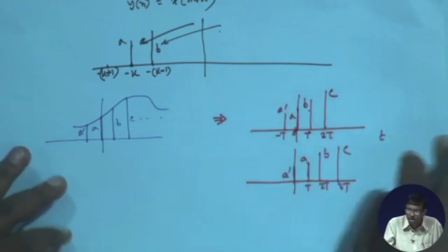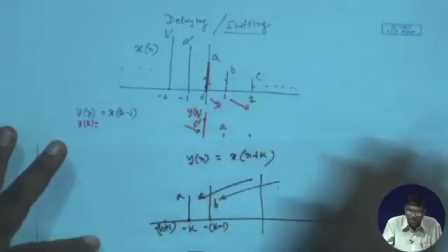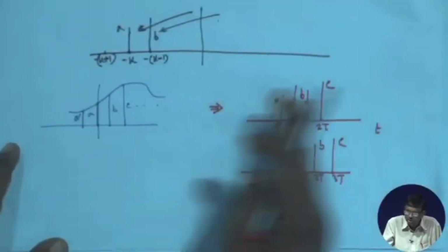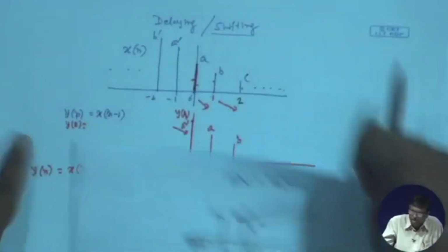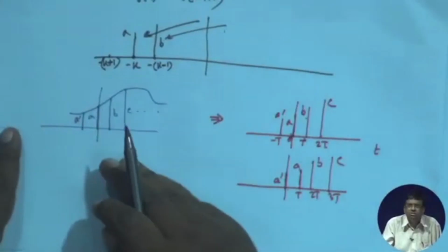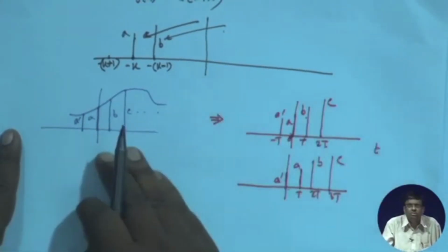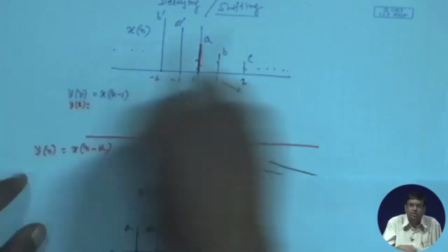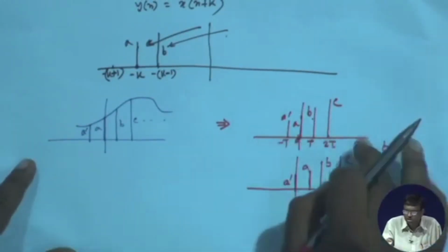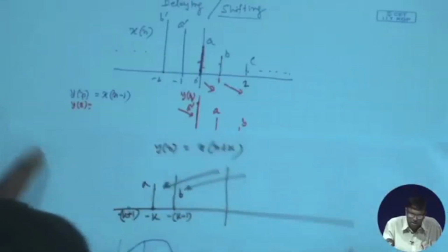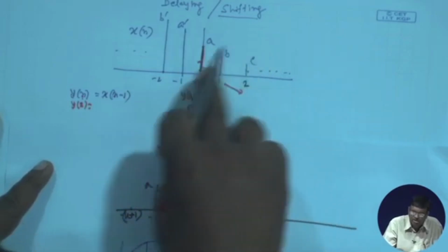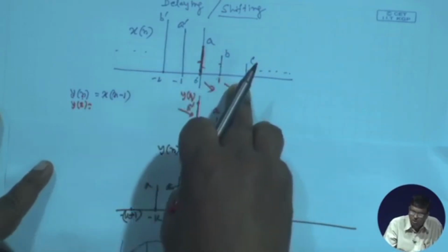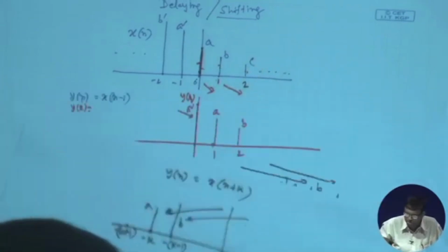Okay. So, if it is a pure time signal, shifting the sequence actually means that in the time domain the signal is delayed, or if it is shifted to the left, that means I am moving it back, so it is advanced in time. So, either delayed in time or advanced in time, but that is when the sequence is obtained from a temporal sequence, a function of time, where this axis corresponds to time. The index points are nothing but sampling points. So, 0, 1 means 1 into T, 2 means 2 into T, 3 means 3 into T.